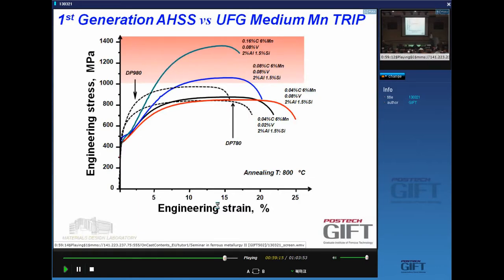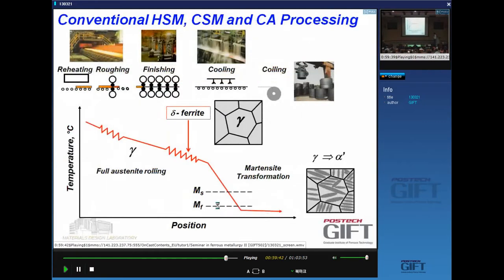Overlaid on this, you see the stress strain curve of some of these intermediate and medium manganese steels. And you can see we have properties that are definitely less than a 100% manganese austenitic steel, but nevertheless very much better than the current industry standards. In addition, the industrialization of this solution of having multi-phase medium to intermediate manganese steels is easier. So you can basically run these materials without much change in a hot strip mill.